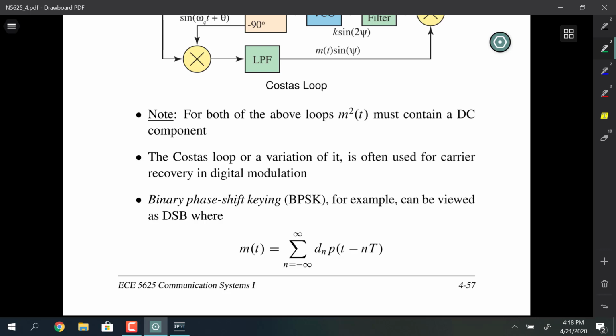And it's often used, in the olden days with more analog type digital comm receivers, for carrier recovery in a coherent digital modulation scheme known as binary phase shift keying, which is something we'll spend some more time talking about in the next couple of weeks. It is in the project, but it's the lowlier modulation, but it's still bread and butter in SATCOM to use